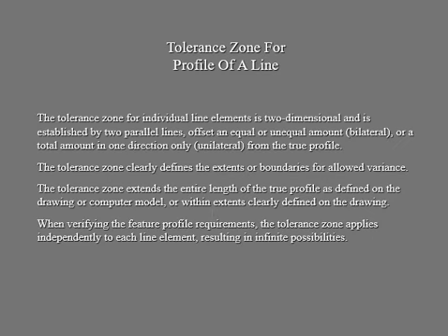The tolerance zone is going to define the extent or boundaries. When you're dealing with your tolerance zone, that's going to extend the entire length of your true profile. Even though we're dealing with the profile of a line, that's pretty much the same as your regular profile. When you verify the feature profile requirement for inspection or verification purposes, your tolerance zone is going to apply independently to each line element. So you have infinite possibilities for verification.